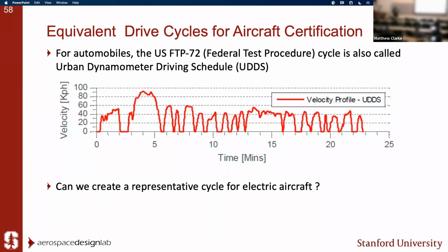The issue with that is when you have phasing, from a dynamical point of view, you have to account for the different torques of the different rotors. These are the small nuances that a lot of eVTOL companies face when they come to us. You have these simple models for motor torque, but technically there is torque in 3 different axes, etc. There are a lot of things that go on in modeling the dynamic loads.